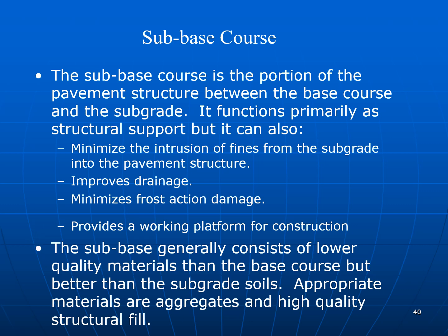The subbase generally consists of relatively lower quality material than the base course, but better than the subgrade soils. Appropriate materials are aggregates and high quality structural fills.